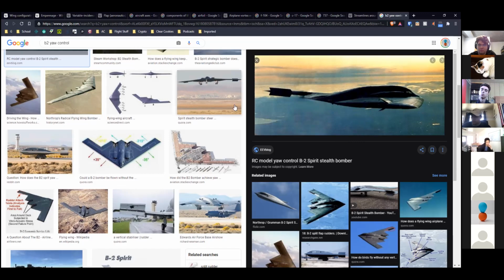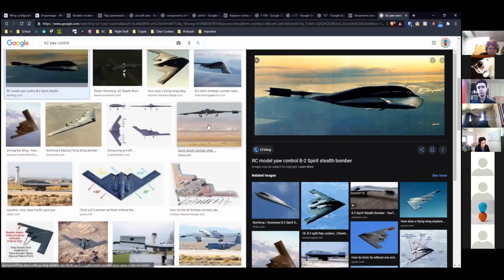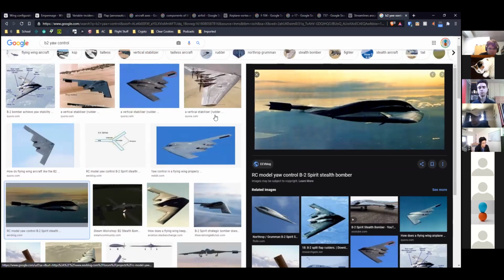But if you give a yaw input, then the computer will factor that in, and you can intentionally change your yaw out of coordination if you want to. Or if the yaw damper is broken or not on, you can control the yaw manually. But most modern aircraft very rarely use that, the pilot very rarely uses the rudder now, especially in jets.